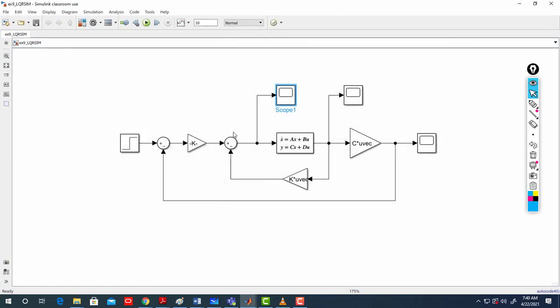Yeah, that's it about this exercise. You see, the architecture doesn't change, just the way in which you are computing K is changed. Of course, you can always try to use the control system tuner app, and the control system tuner app most likely uses the optimal control method, in which they don't choose pole location, but they do iteration of Q and R. So now when you set your goals, that's internally what's going to happen. Like, you see optimal control, you cannot learn before learning state space control. So that you see the same architecture as applied. You need to use gain matrices.